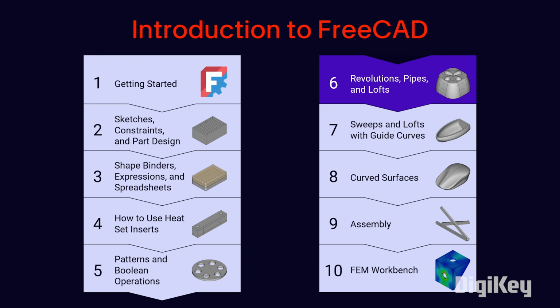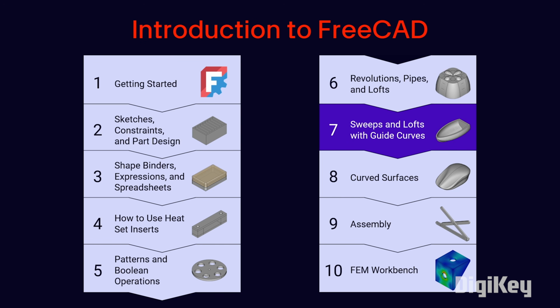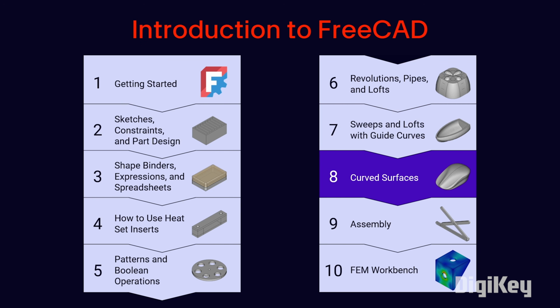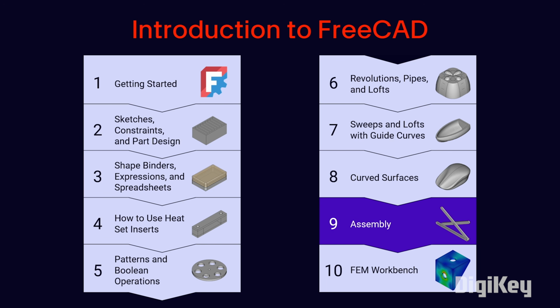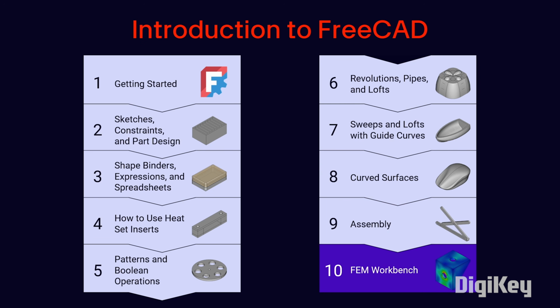As a result, we'll need to look at the Curved Shapes Workbench, which is a third-party add-on that makes working with lofts along guide rails much easier. We'll also look at the Curves Workbench for doing organic shapes. Finally, we'll examine the Assemblies Workbench to see how parts fit together, and then the Finite Element Method, or FEM Workbench, for simulating stress and failure points on designs.